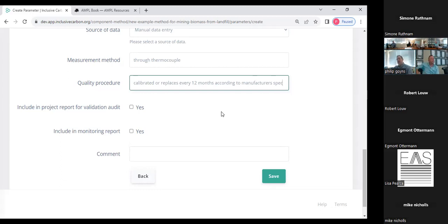But again, that comes down to you to define how that adjustment would be calculated. Quite often what's done is you can look at the tolerance and the error that gets measured during calibration. And then you can adjust the values that you measured by that error that was picked up during calibration, retrospectively.